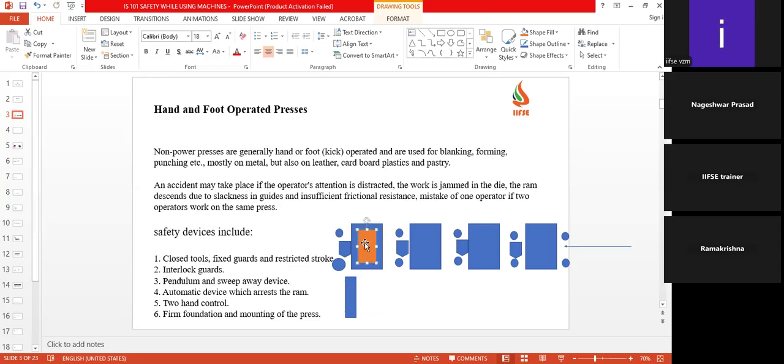And even while the die is coming out, we have a photoelectric sensor so that they will not interact with it. If the photoelectric sensor is interrupted, the die will immediately stop. Apart from that, it can be operated in automatic mode, where four robots are used separately for shifting each part from each machine, one by one, from left to right.